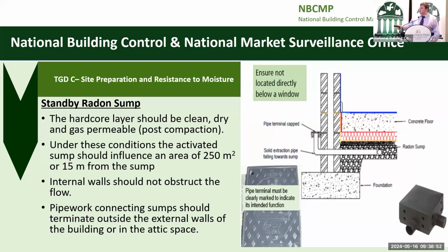Also the products and identification on the marker outside. And if you're in the red areas, I would recommend that you actually extend the pipe up and carry out your testing, because at least you know that you're in a high radon area. And remember that building regulations are minimum requirements. There is nothing stopping you going above that requirement.